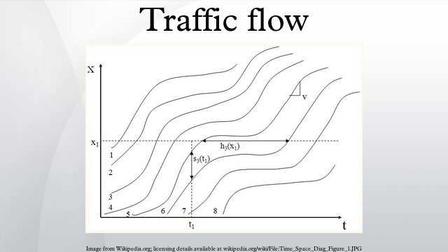Moving bottleneck. As explained above, moving bottlenecks are caused by slow-moving vehicles that cause disruption in traffic. Moving bottlenecks can be active or inactive bottlenecks. If the reduced capacity, Q, caused by a moving bottleneck is greater than the actual capacity, μ, downstream of the vehicle, then this bottleneck is said to be an active bottleneck. Figure 20 shows the case of a truck moving with velocity V approaching a downstream location with capacity μ. If the reduced capacity of the truck is less than the downstream capacity, then the truck becomes an inactive bottleneck.